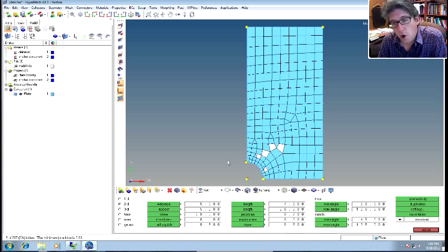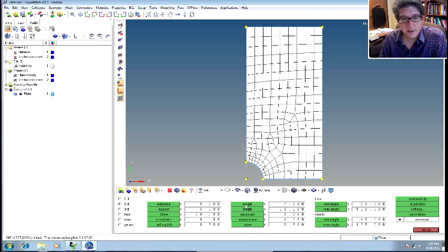I could go back and refine the mesh to a point where those Jacobians get above 0.7. Generally, if you have all Jacobians between 0.7 and 1, you usually have a very good mesh. You have other things you can check, like warpage. It looks like all the elements meet warpage, aspect, and skew. We don't have to worry about length. That scales out, really big ones or really small ones, but Jacobian seems to be the problem here.